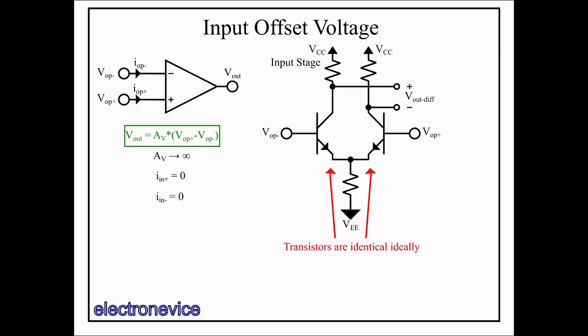The transistor circuits are matched by having them close together during fabrication, so that the doping concentrations and doping regions of the parts of the two transistors are very similar. There are also many proprietary processes and tricks used by semiconductor manufacturers to improve the matching between them. However, there still is a mismatch between these two transistors, as well as the other elements in the two sides of the input stage, such as the resistors at the top. They cannot ever be perfectly matched.